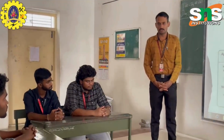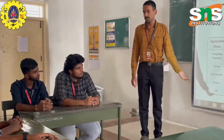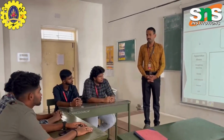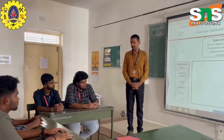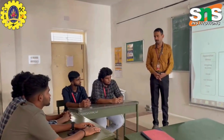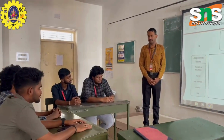The use of poorly graded soil in construction is the main problem. We have to collect samples from various construction sites, perform Sieve analysis and find out whether the soil is capable of being used further during the construction process. For that purpose we have implemented Sieve analysis to categorize the soil, whether it is capable of performing or not. This classification plays a vital role in soil maintenance.